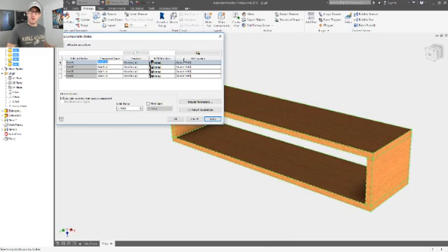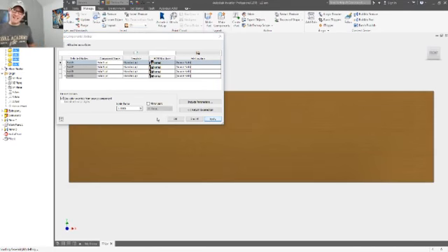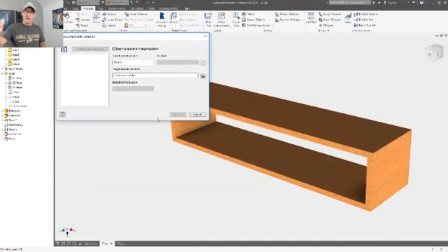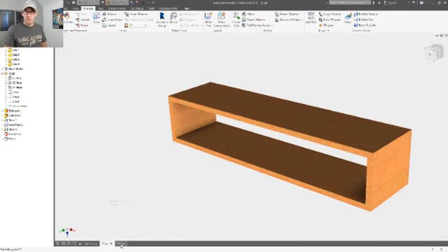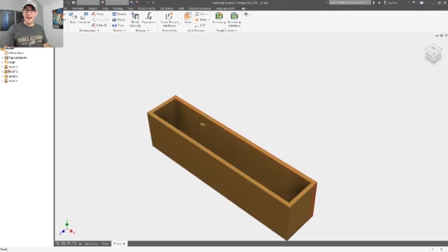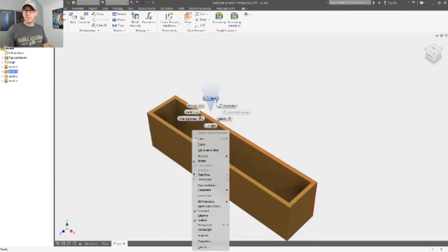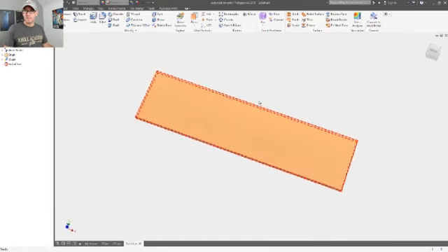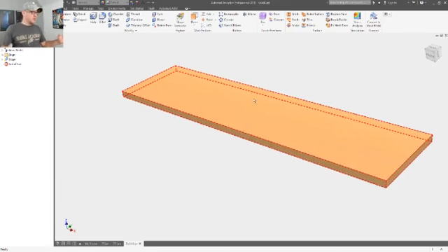It tells you where they're going to go. It's just going to go in the default location. It's a standard part file. There's no scale factor. I hit apply. It's going to save all 4 of those parts as individual components. You're going to see now what I have is I have a 22 assembly file, and inside of this 22 assembly file, I now have individual components. So those of you that like doing multi-body parts like I do it all the time.